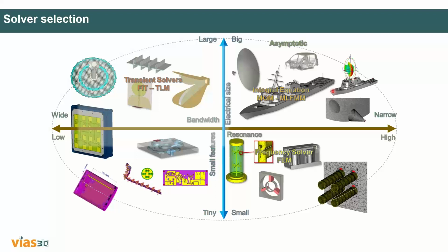But that cannot be used for extremely electrically large structures. That's the reason the ray tracing methods are more preferred. We call it asymptotic, because they are not as accurate as these full wave methods. This is called a full wave method. They are using the brute force technique, right? They are directly implementing Maxwell's equations, even though saying brute force method is an exaggeration, you know.